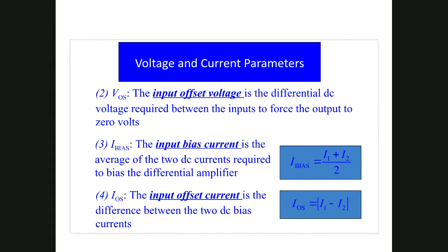The same with op-amp. A perfect op-amp should have output zero, which is not the case, because you know very well that this operational amplifier needs DC voltages to work as an amplifier, and these DC voltages give some output even if there is no external input available. You're getting my point? So to cancel this, we apply some input voltage in such a way that it will cancel the effect, and the result after applying this input voltage will be zero. This is what is input offset.